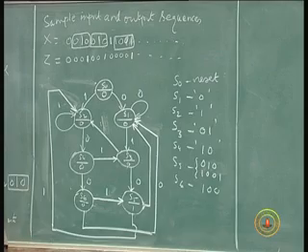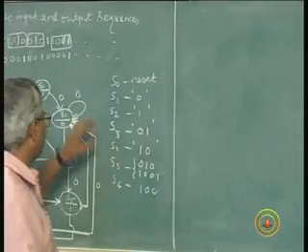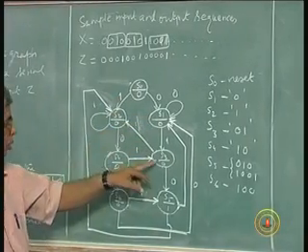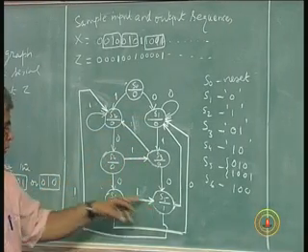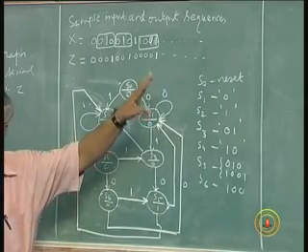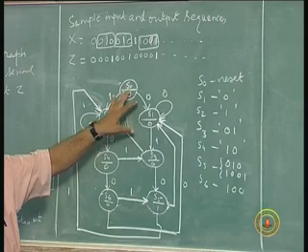Again, you use 3 flip flops. You can draw the state graph with the present state values arbitrarily assigned as 0 0 0, 0 0 1, 0 1 0, 0 1 1, 1 0 0, 1 0 1, 1 1 0, and then the input x is equal to 0. What is the next state? What is the output? Of course, output is dependent on the state now.